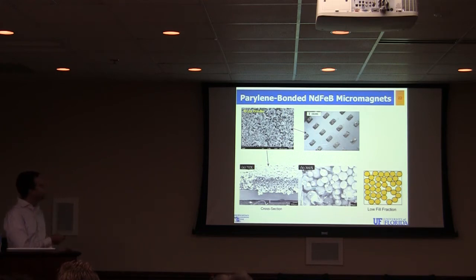And this is the one where it is parylene vapor-coated. If you cleave the wafer, the parylene comes in and infiltrates down through this matrix and puts like a shrink wrap coating on all the particles. So all the particles are held in place. When you cleave it and tear it, you can actually see these white spots where that shrink wrap polymer coating has been torn away, for those of you that don't know what parylene is. But one limitation of these monodispersed spheres is you get a lot of void space and a fairly low fill fraction, maybe only 40% by volume.